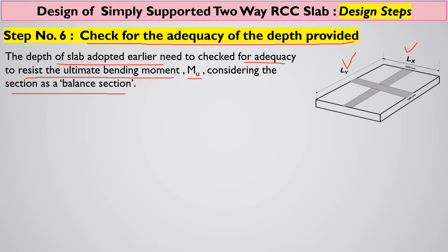So whatever calculation, reinforcement, bending moment, etc. we are doing, we are designing these two strips, and ultimately, similar to a one-way slab, whatever reinforcement we get will be adopted throughout the slab along both directions, that is parallel to Lx as well as parallel to Ly.